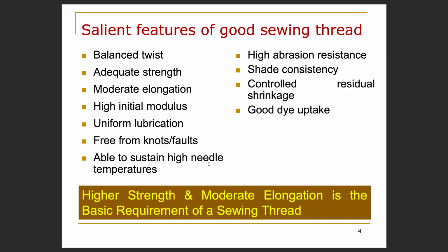So the needle will get heated up, and the needle temperature will rise. In such circumstances, the sewing thread should be able to withstand that high temperature. It should not melt because of the needle heating. It should have high abrasion resistance.